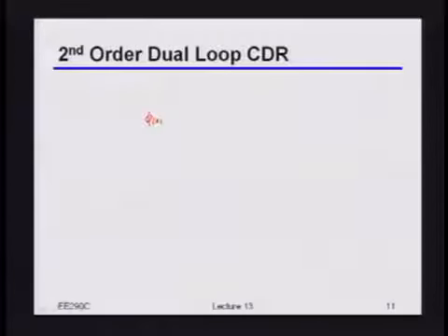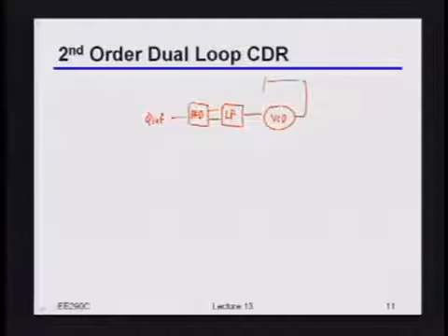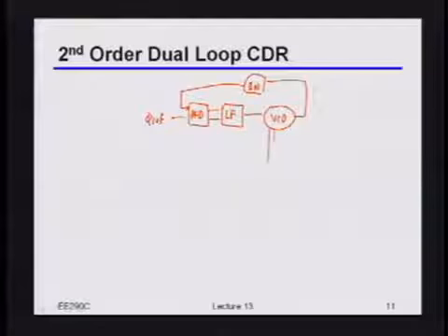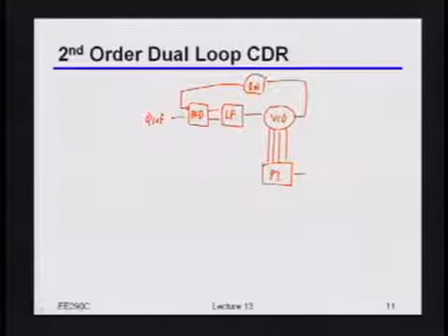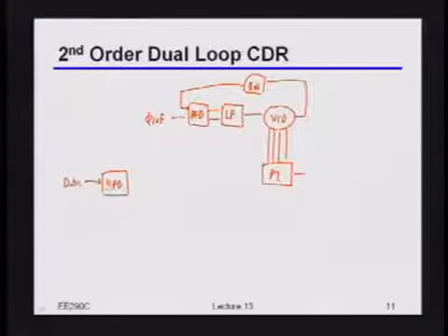Okay, so again, we're going to have some reference clock. We're going to have some main so-called clock generation PLL that we're going to use to generate that clock. So again, our standard PFD, loop filter, VCO, and of course feed that back, divide by some N, feed that back to there. Then again, I'm going to take the multiple phases out of that VCO and feed that into some phase interpolator. And of course, just like before, I'm still going to have some bang-bang phase detector. So this is my data, and feeding into here is my either data or edge clock. Okay?